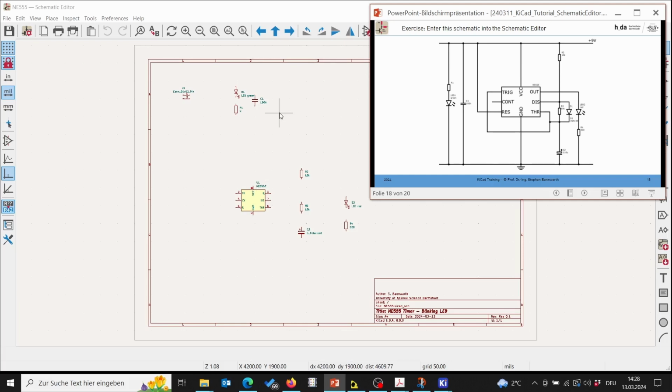That's why in bigger schematics we don't draw the power supply lines anymore, but we use the technique of connecting by name. What does it mean? This means we put here some symbol or a wire, and we label it, for example, VCC for the positive power supply, and then we connect here also a wire, name it VCC, and then these two wires are connected. So later on in the PCB layout program, the layout program knows that we have to make a trace from this device to this device, but in the schematic it's not shown, it's connected by name.